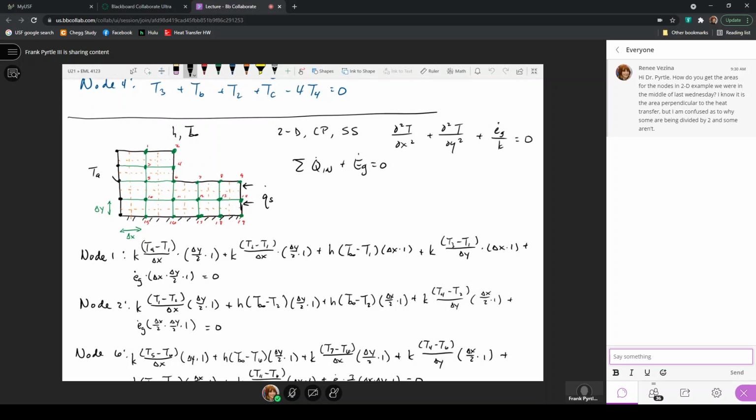and a third domain to represent a rectangular section, because if we're solving this problem, this was the reduced expression of the general heat equation, we'd have to have just 2 boundary conditions in the x and 2 boundary conditions in the y for a particular domain. And so we'd have to split this entire domain into 3 subdomains and then write expressions of an equality of the fluxes across the boundaries where we make these artificial or imaginary cuts in the total domain, so that there will be a balancing of the heat fluxes across those boundaries.